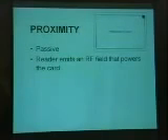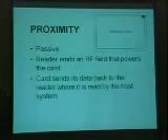Actually, it's a coil of a bazillion turns of the finest wire you will ever see. So basically, it powers up, it's magnetically coupled, and it barfs back a data stream. It takes 506 bits across the air interface to hand over a single 26-bit ID. So there's a lot of redundancy in it.